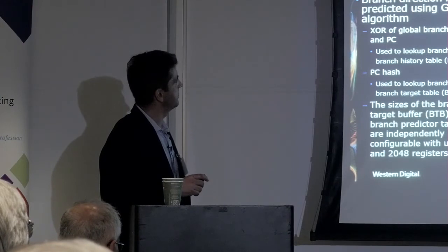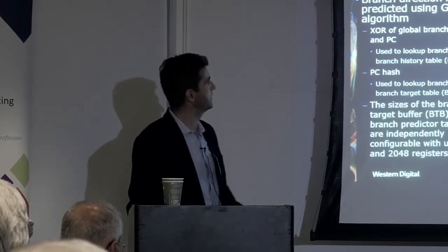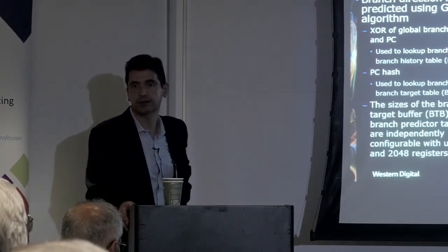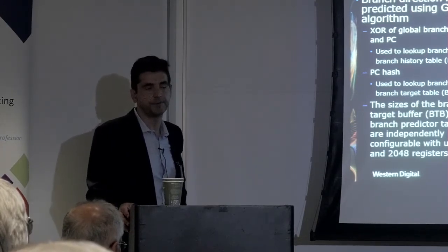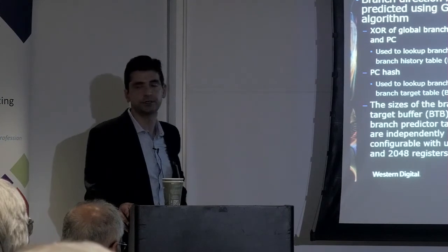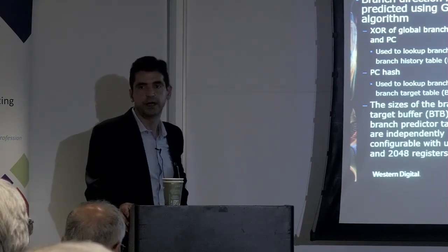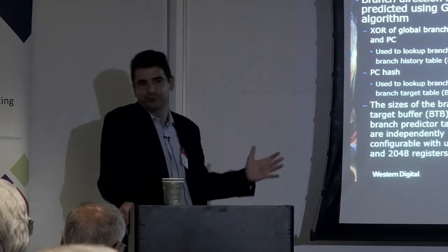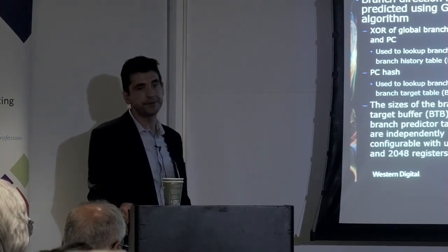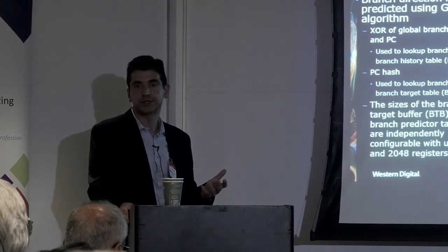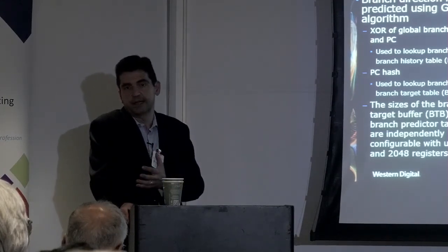In terms of branch prediction, we implemented a branch prediction algorithm called GShare. GShare is one of the branch prediction algorithms described in the Patterson book. To understand it, you have to read all the previous ones until you graduate to GShare. This is about the most complicated branch prediction that makes sense in embedded applications.